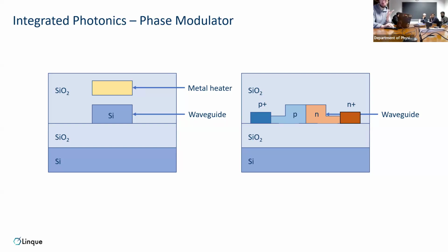But they're very, very, very fast and very mature. Currently the foundries are working on getting those mature enough at a modulation frequency of around 100 gigahertz, which means that with certain modulation formats, you can get 400 gigabit per second of transmission on a single wavelength channel.